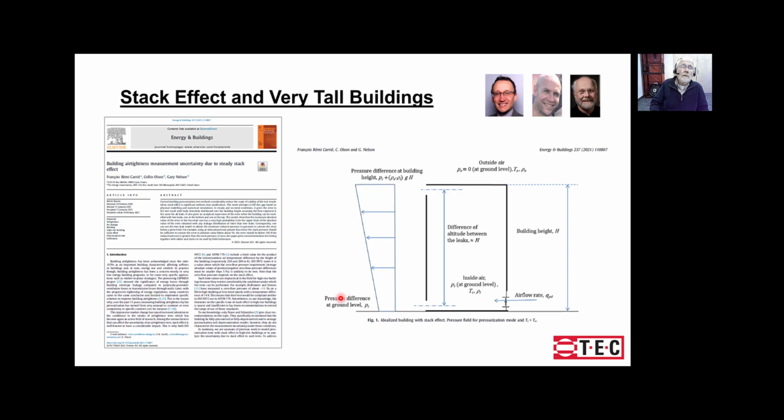And the motivation for this is that when you're in a tall building, there are standards that require that at the beginning of a test you measure, in Europe they call it the zero flow pressure, we call it the baseline pressure. But if the baseline pressure is above about 5 pascals, I believe, in this European standard, you're not allowed to say that you have a valid test.